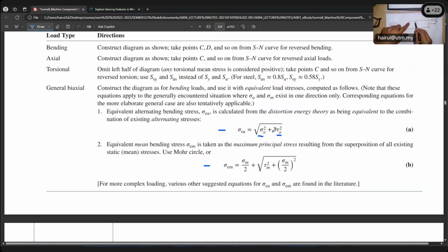So at the notch here, because this is the radius of the notch, the stress extends a little bit, elongates, and then the curve goes back to the average, F over area. But this one extends a little bit. Understand that, class? Even for axial stress, because of this notch. When you have a notch, a curve with a small radius, we have a stress concentration. It elongates a little bit, so this is higher.